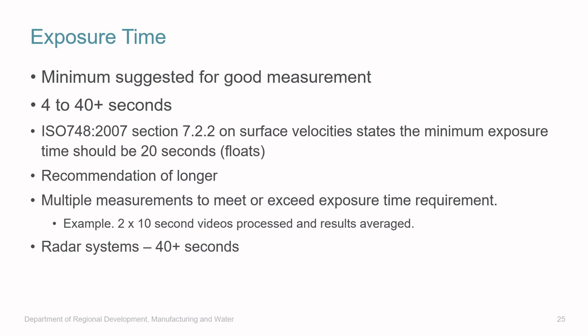Exposure time was one that received a particular amount of feedback from the review, and suggested times given to us were from 4 to 40 plus seconds. However, ISO 748 already has a recommended exposure time of 20 seconds for float, so we have decided to align ourselves with that for the time being, with a recommendation of longer. Multiple measurements have been allowed to meet or exceed the exposure time requirements.